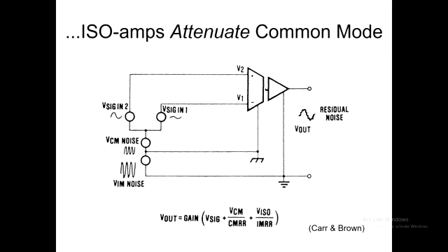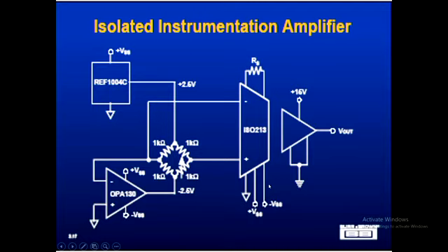Okay, so there we have it once again. Isolation mode noise between two different reference points or grounds. Common mode with respect to one ground. Cancellation occurring by subtraction. It kills off the common mode noise. The attenuation kills off the common mode as well as the isolation mode noise. Okay, do we know enough about bridge circuits to understand how this one works, I wonder?